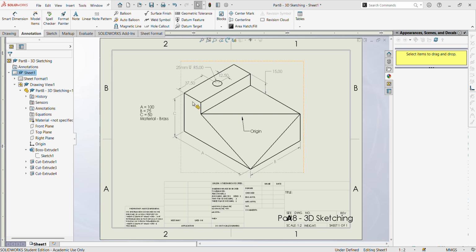With something like this, it's not too crazy useful, because again, it's just length, width, and height. So say you did need to change any one of those, you're only working in the sketch for length and width or height, and then the extrude for the last variable. So you really would just right click, edit, change the one variable, and it would fix it. But you can do the same thing here in equations and global variables. Cool. So just know that it's useful most of the time, not all the time.